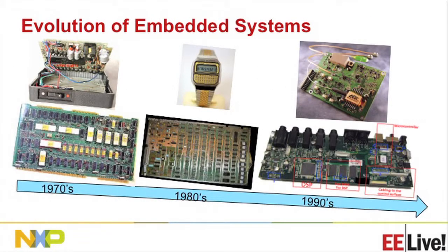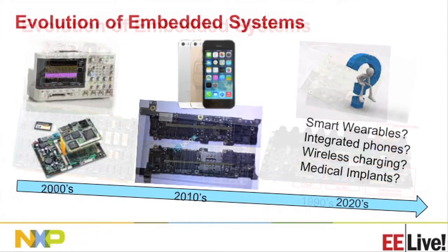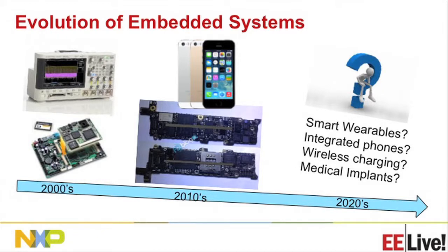So a bit of history about embedded systems. In the 70s, we had bigger boards. The popular packages were DIP. The trend continues into the 80s, where you would see the SO, SSOPs. Boards became slightly smaller. In the 1990s, the trend continues. TSSOP dominates. And these are 16-pin or more packages on the board. Coming into 2000, the trend continues. You see more and more size shrinking, smaller systems. The popular packages are becoming leadless packages, which are QFNs, thinner packages. And this is what we see in smartphones today.